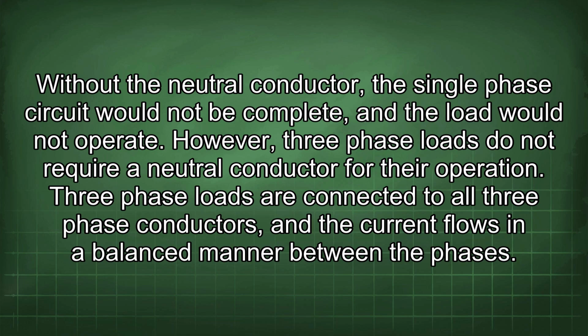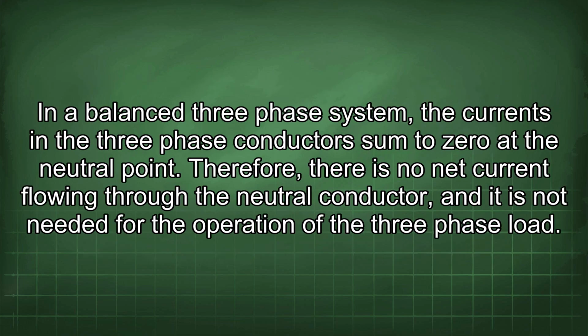However, three-phase loads do not require a neutral conductor for their operation. Three-phase loads are connected to all three-phase conductors, and the current flows in a balanced manner between the phases. In a balanced three-phase system, the currents in the three-phase conductors sum to zero at the neutral point. Therefore, there is no net current flowing through the neutral conductor, and it is not needed for the operation of